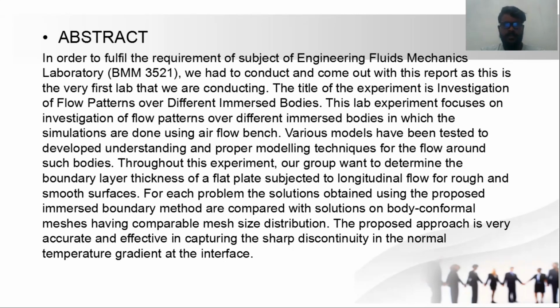The title of the experiment is investigation of the flow pattern over different immersed bodies. The lab experiment focuses on the investigation of flow patterns over different immersed bodies, in which the simulations are done using the airflow bench. Various models have been tested to develop understanding and proper modeling techniques for flow around immersed bodies. Throughout the experiment, our group of three wanted to determine the boundary layer thickness of a flat plate subjected to longitudinal flow for rough and smooth surfaces.